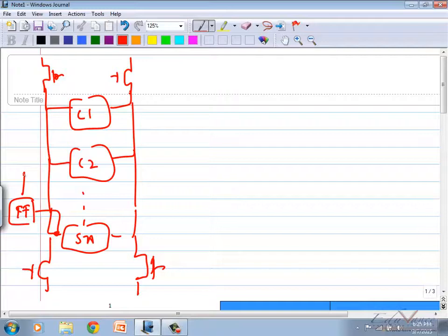Correct? Yes or no? So, typically with every SRAM you have something called an SRAM controller also. Setting precharge to 1, then this to 1, that to 1, all of it has a timing, right? Who handles that? That is handled by your SRAM controller. So a lethal SRAM chip design project is not only the SRAM memory part with the decoder. I'll explain why you need the decoder and your sense amplifier, but you also have your memory controller. It must be designed. If you want to do a very cool BE project, then do your SRAM with your SRAM controller. That will be a lethal BE project.